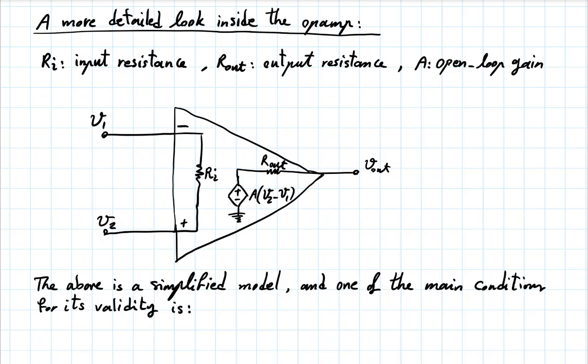Okay? So how are those supply voltages in the top diagram related to these components? The answer is they are not directly related to this. If you want to see where those supply voltages connect, you have to look at the full op-amp circuit. And that op-amp circuit might have 20 components, and you will see where everything is connected. This is not the op-amp circuit, but this is a model that represents the function of the op-amp. So that's a very good question, and it's important to keep in mind that this is a model